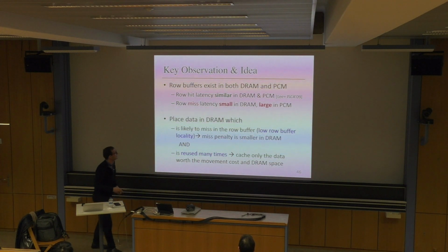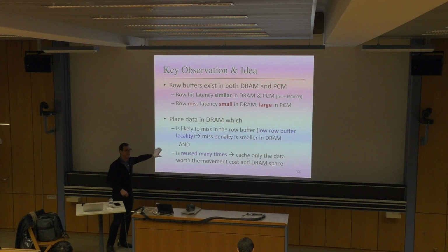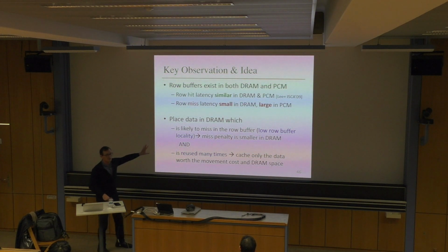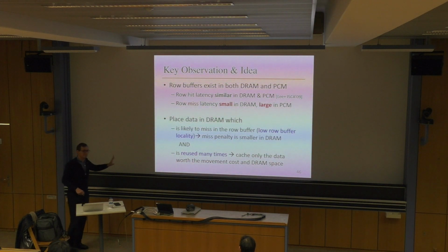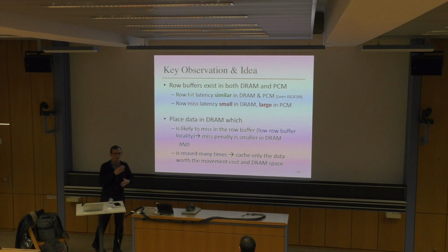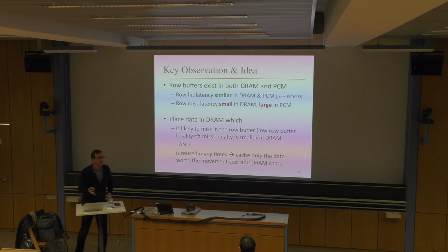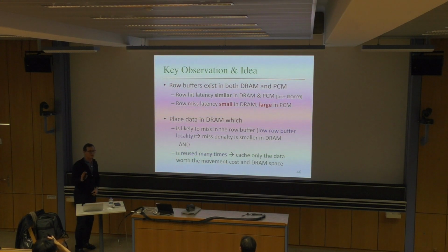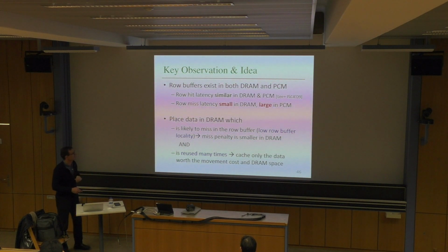That's the idea. Okay, so how do you do this? It's written in the paper. It basically has a hardware-based mechanism to detect what accesses are streaming and what accesses are random. You could potentially do it at the higher levels, right? The compiler can mark the access as streaming versus random access. That's also possible to do. Or the programmer can indicate hints as to which accesses are random, which accesses are streaming. That's also possible to do. We did it in hardware. I think hardware is a good place to discover these. But if you have higher level information, you can feed it also into the hardware.